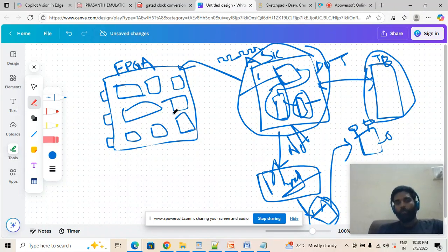So FPGA provides some dedicated blocks called block RAMs. It's called BRAM, or URAM in the latest FPGA parts. It supports some URAM, which is a little higher capacity than the BRAM. And also we have this distributed RAM. Again, I said it will be common resources. So we need to aim for this kind of memory resources. So we need to map this RAM into our dedicated block RAMs, right?